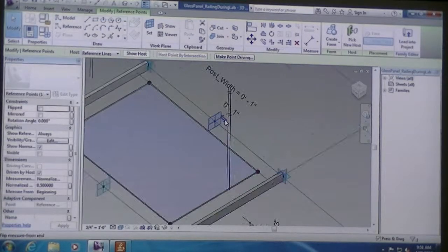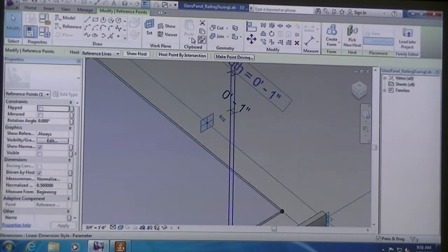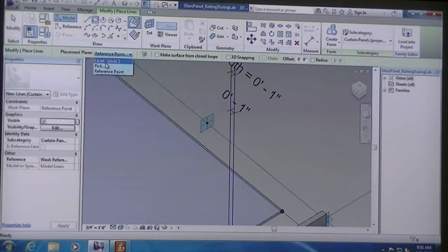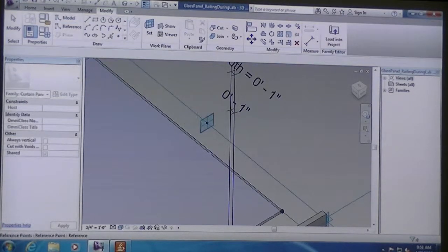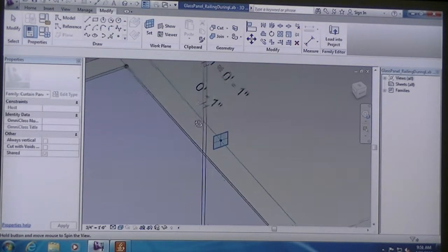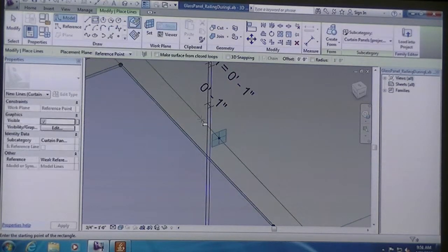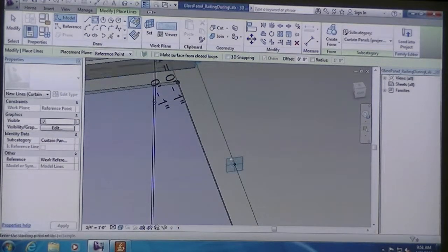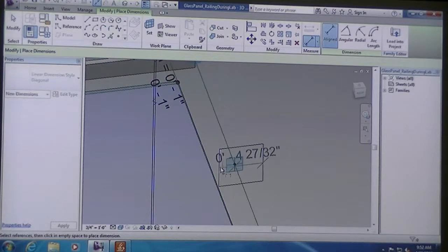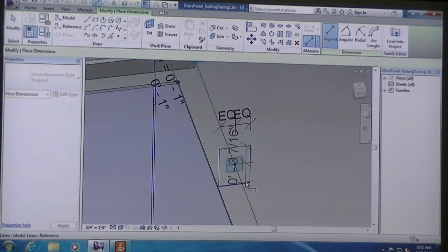So now I'm just going to, on this particular point on the plane, again draw another rectangle. So you can see this is very similar to drawing the profiles for the rail and then using the rail command, but we're having to kind of force exactly where the height is located. I need to rectangle. And then I'm going to draw my dimensions equal on top and bottom.